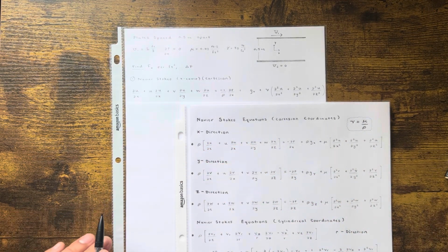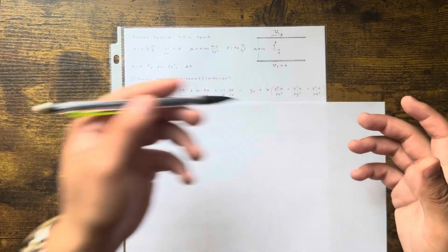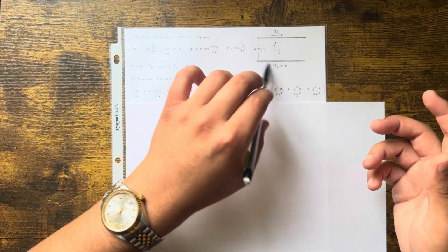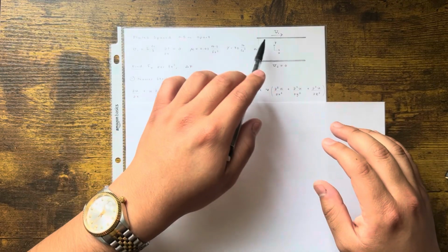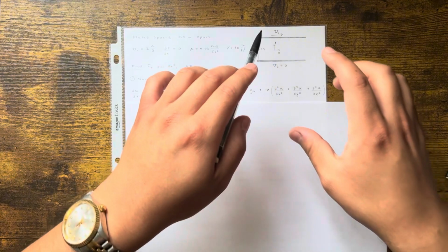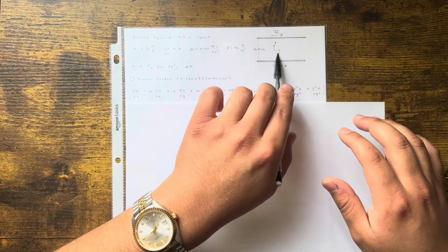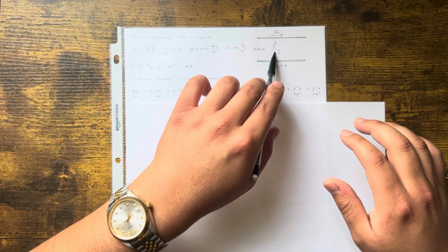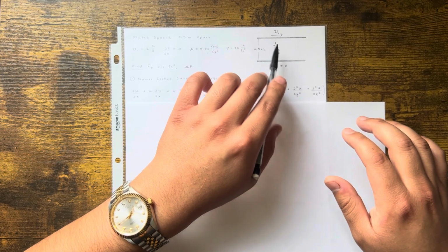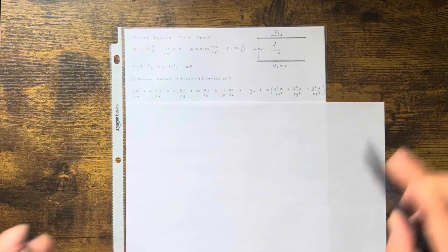So nothing really changes. That is the equation we use, because that is the direction that the flow is going in, right? So we chose our coordinate system to follow the flow. So it's just xy. And the reason I say that is because some examples sometimes will tell you there's an inclined plate, and you might have to tilt this axis to follow that incline and to make your life easier. But in this case, they're plates, so you're using xy. In a tube, you would use the radial direction, cylindrical coordinates. My bad, went too quick there.